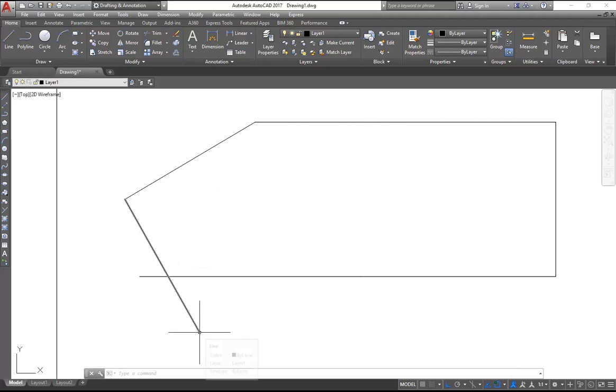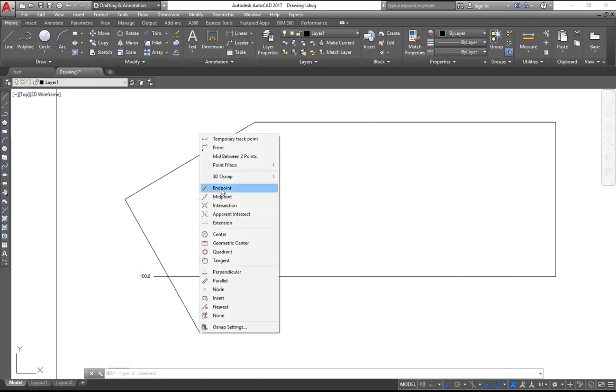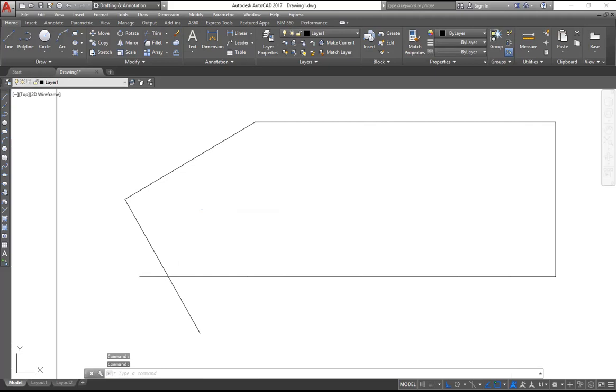So all I want to do now is to be able to get this line to cross and I want to lengthen or shrink this line. Okay, you can use stretch or lengthen to bring this line to the intersection. Now, wait, before this, I will need to right click and say intersection so that it will help me to really get that. So I'm going to hold it when it turns to red, and I'm going to bring it to intersection. Now I'm having a problem here. I'll click there. Now you can see because I'm having orthogonal on, so I have a problem to get that. So I can turn off my orthogonal mode.